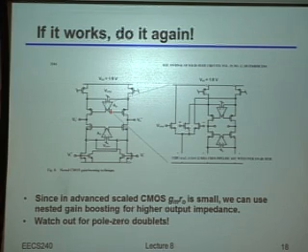Okay? So you can imagine you can keep applying this recursively, right? If you don't have enough gain from that, you can take the next amplifier inside of here and gain boost that as well, and so on and so forth, up to whatever ridiculous gain you happen to feel like getting. So this indeed works. It's a very clever trick. But there's hopefully one fairly obvious and perhaps major annoyance with this. So what's the major annoyance given the long discussion we just had?